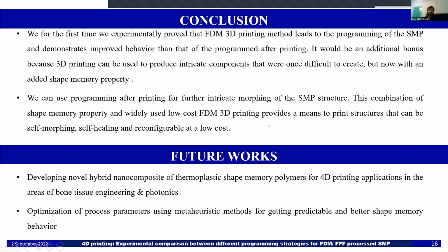Coming to the conclusion, we experimentally proved for the first time that the FDM 3D printing method leads to programming and also shows improved behavior than programming after printing. We can also use programming after printing for further intricate morphing of the shape memory polymer structure after printing.